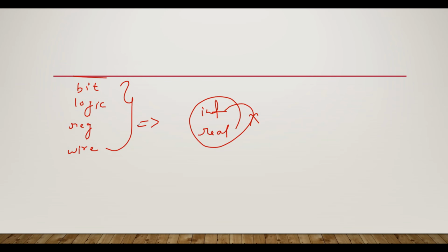But before that, let's see how to write a packed array and how memory is formed. Suppose you have written a multi-dimensional packed array, something like this: bit [3:0][7:0], and you have given it a name like array. So how is your memory formed?